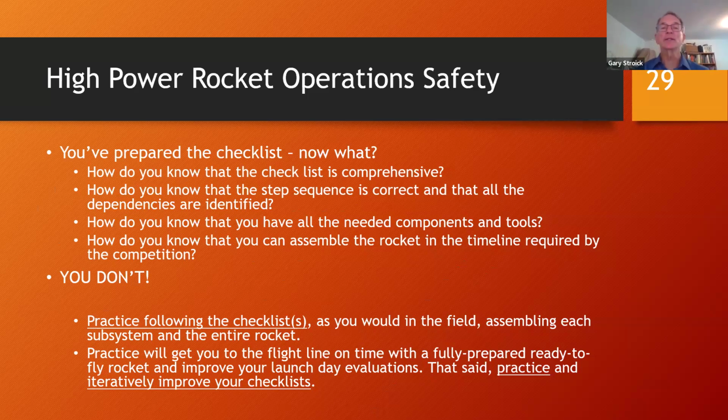So you really need to practice going through your checklists as you would in the field, assembling your entire subsystem and rocket. And by the way, that excludes the charge, at least using black powder. You can use a substitute substance, but not black powder, right? And it also excludes the motor. You can use a substitute pretend motor, but not the actual motor. We don't want you doing that in your classrooms or wherever, or in a house or whatever the case may be.